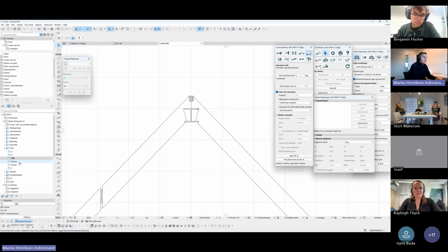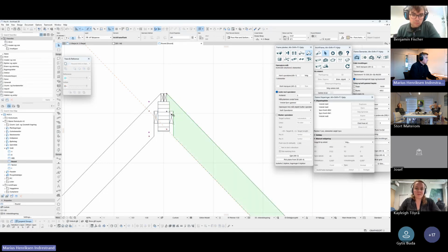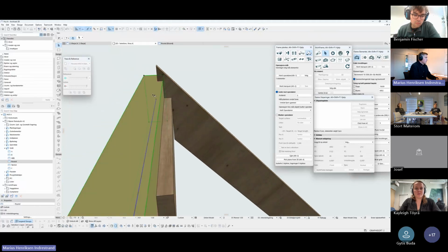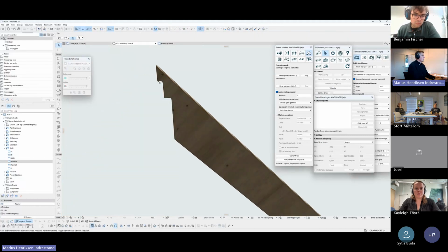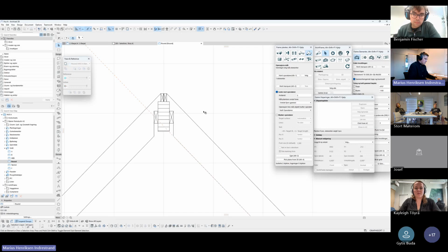And this is not VCut, but I think it's important, at least if you do special kinds of things that you haven't done before, always check with the Hundegger operator or in the SpeedCut program. In this case we have the glue laminated and the rafter. It's kind of hard to see, but if you delete this, ArchiFrame produces this with a rounded piece.